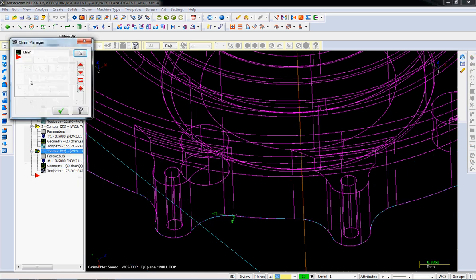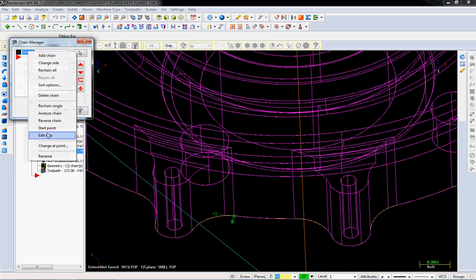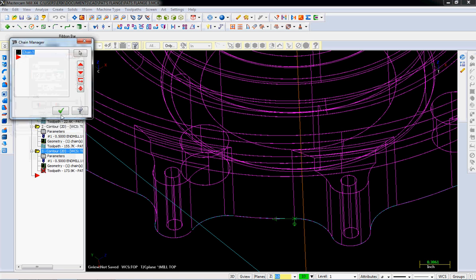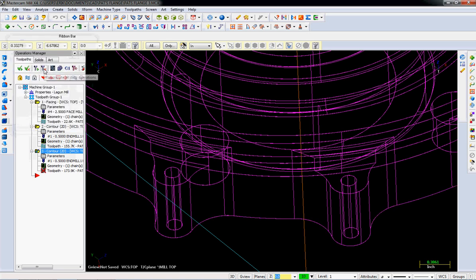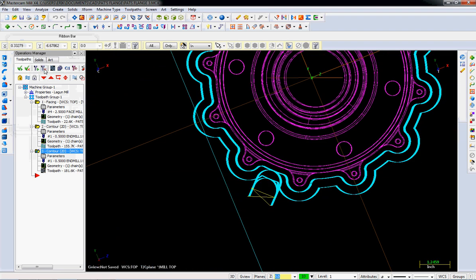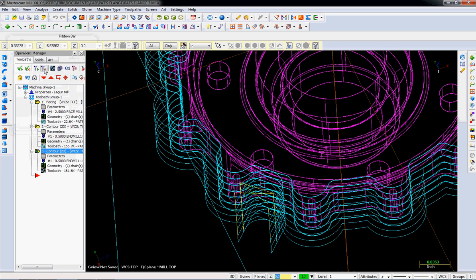in that corner. So let's go back in here, and realistically, let's see, what can I do? I can right click here and let's change the start point. I can tab around, so it'll jump vertex to vertex, and now this has got more room for the lead in, lead out. I prefer that Mastercam was smart enough to figure out how to deal with that, but oh well, this isn't too tough to change the start point. Okay, and let's redo the dirty operations, and sure enough, we've got ourselves some lead in, lead out that look completely reasonable.